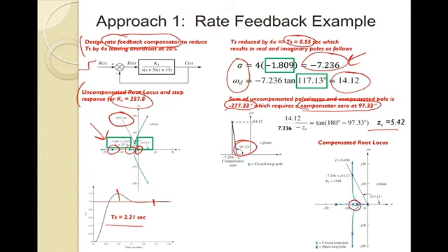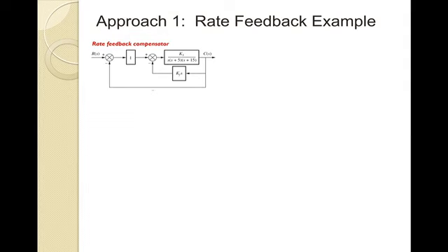What we can now do is vary our root locus and see where we get on that damping line to give us that 20% overshoot, and we get a K, in this case, of about 1388.